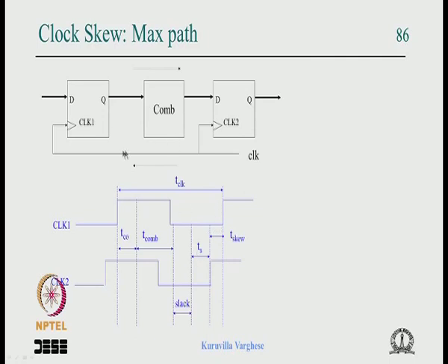Now assume that there is a clock coming to clock 1 and clock 2. For the same clock edge we need not worry, because TCQ plus TCOM is greater than the skew. By the time this first clock comes at both places, there is no time to latch whatever is propagated, because it is already gone and the data comes later.